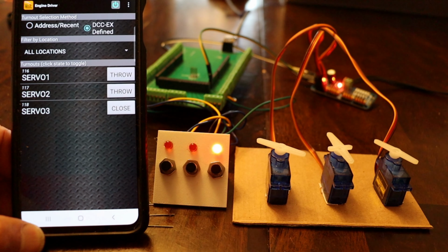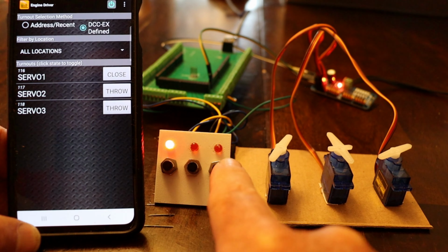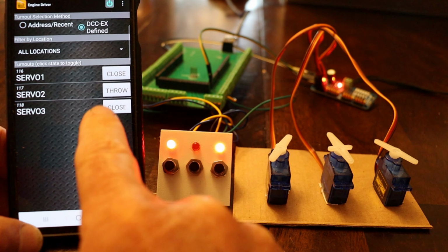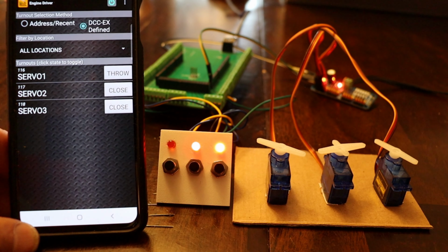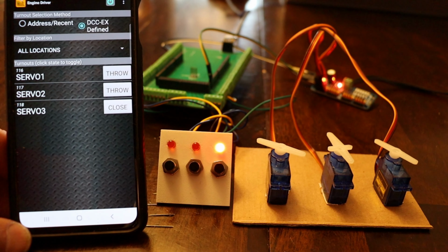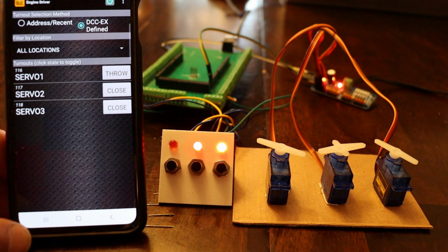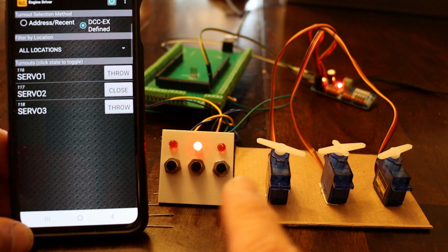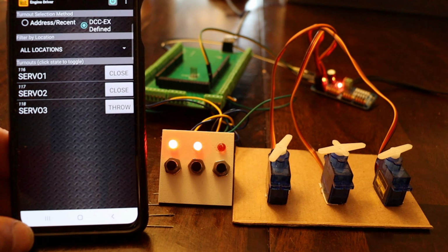And since you're in here, you can also still come in and override the script. So you can tell it to do it, and of course everything updates. Same here too. If you still come in here, it still controls the servos. The only thing to be careful is you've got an automated script running, you have trains running, and you've got switches set, and that automated script is changing these turnouts for your trains to run through. If you come in and override it, you could be setting yourself up for an accident or a derailment or something. So it is available, it is there, and certainly there are reasons why you might want to do this, but just be careful when you override whatever you have written in your automation script if you're using that.